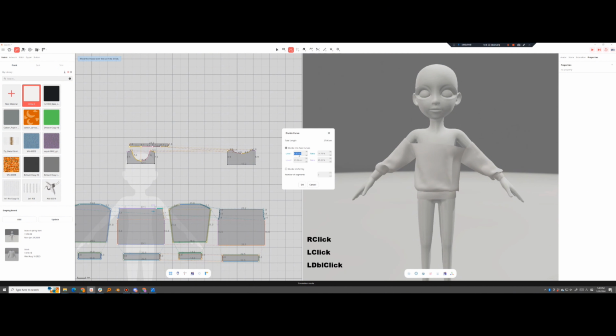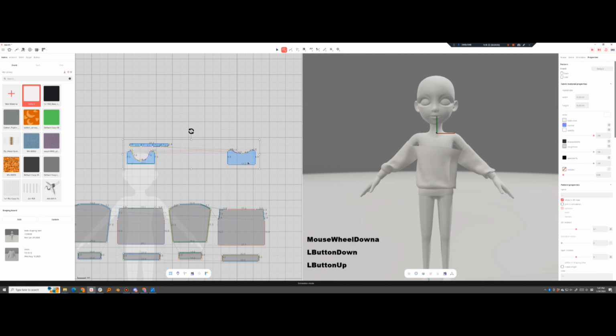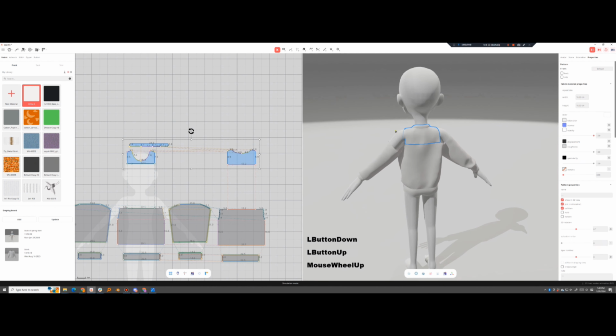By dividing the curve, make the dot points with the same length as the top bodies. We're going to have 4 cm apart from each side. These points are to locate sewing lines with the top and bottom bodies. Sew the top and bottom bodies with single sewing. Then select all top pieces, right-click and turn on Join-in Simulation.